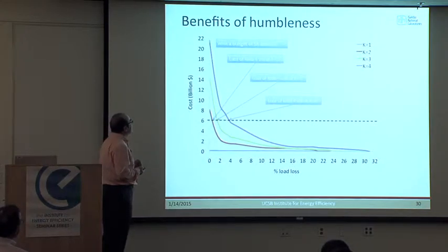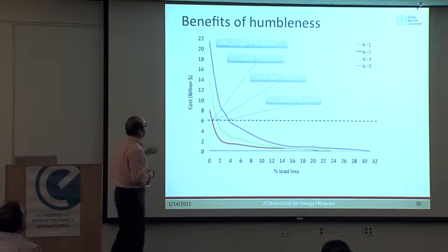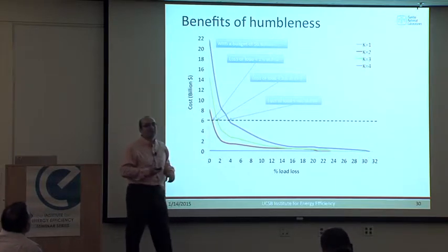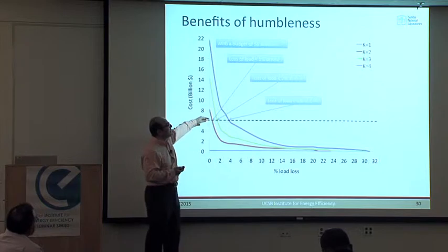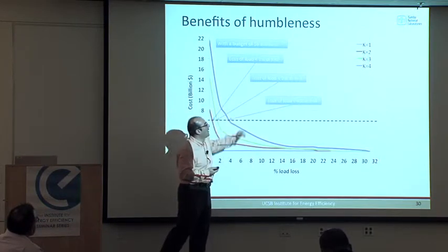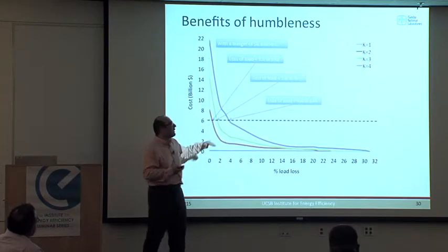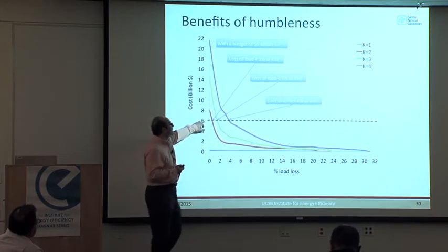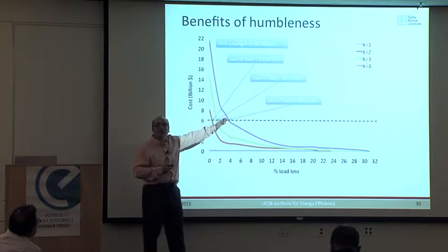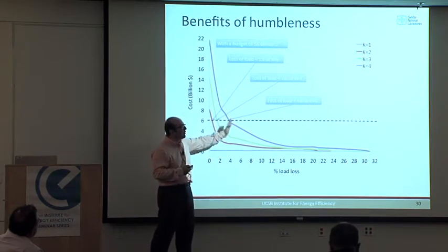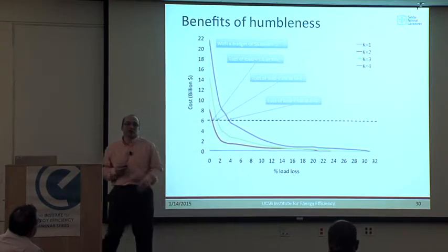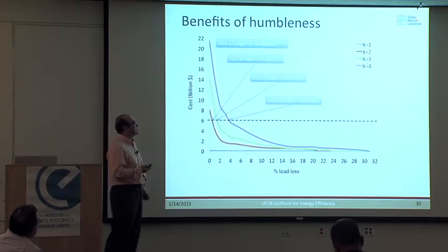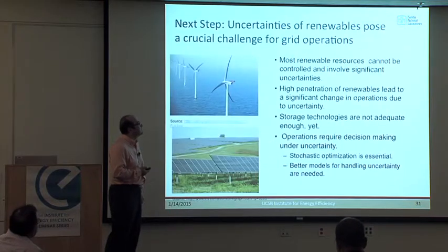And so here, if this is my budget, how should I set the allowable loss of load at different places? In this case it tells me, you should allow for k equals 4, if I lose 4 lines, to go ahead and allow 4% of the load to be shed. And that's how the analysis allows me to set the expectations for these problems.